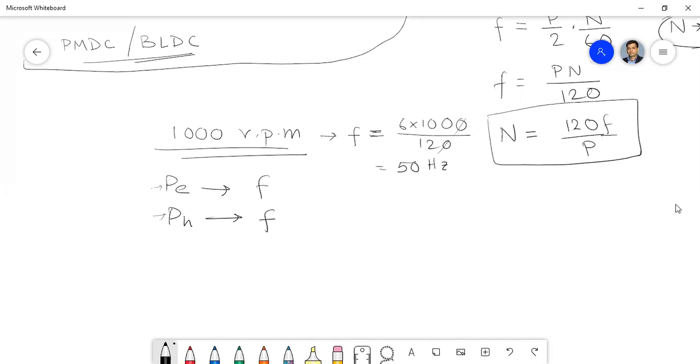Sir, the magnetic circuit path completes through the yoke and the poles. The flux going through the pole is also not time varying, so lamination is not needed there? Correct. As the poles are also static in nature, the flux which flows through them is not time varying. So poles may be made of non-laminated steel or iron.